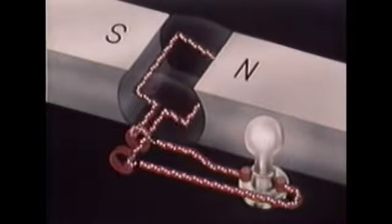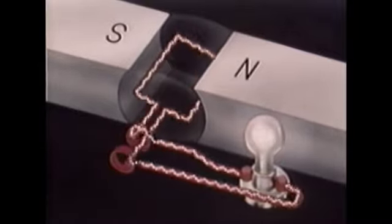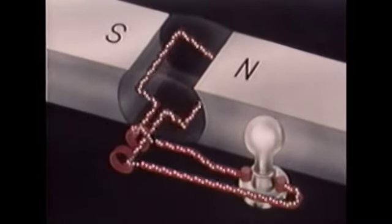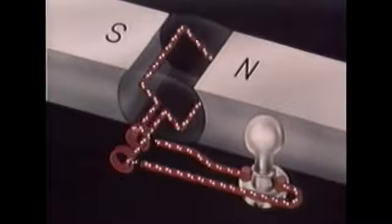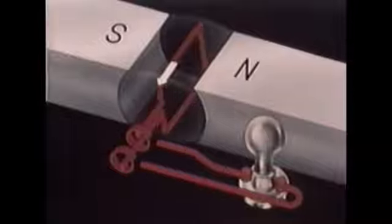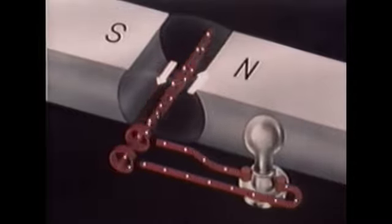As the conductor continues in its rotation at a constant speed, it cuts through the magnetic field slower and slower because it moves at smaller and smaller angles to the field. Therefore, less current is induced. When the conductor moves parallel to the field, no current flows because the conductor doesn't cut through any lines of force. This occurs twice in each revolution. As the coil rotates, one of its sides cuts downward through the magnetic field, causing current to be induced in one direction, and while one side moves downward, the other side is moving upward, inducing current in the opposite direction.